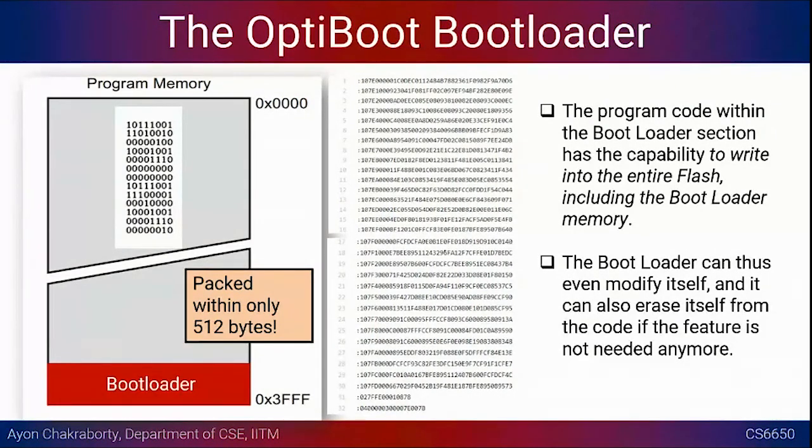Often you don't need this bootloader. Whenever your program starts, it could start from 0000, which could be the default value, and then you keep on executing your program. Nobody is going to load any program later. This is production hardware, so you don't need to change anything there. So a bootloader can even modify itself, and it can also erase itself from the code if the feature is not needed anymore. You might not need a bootloader, and this is from the manual, the Atmel manual. You can check that out.